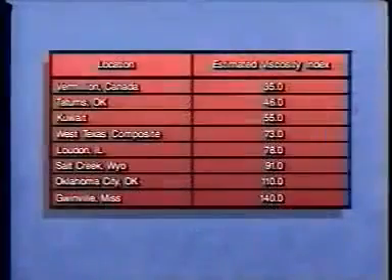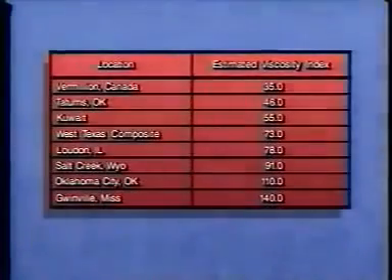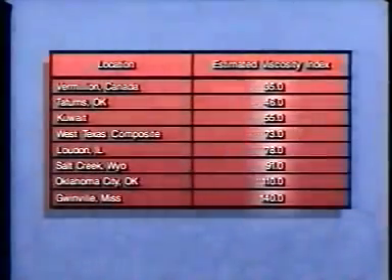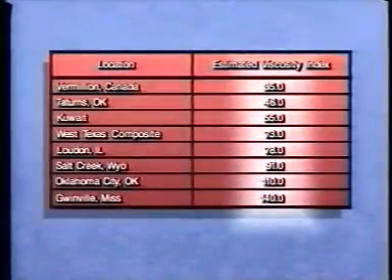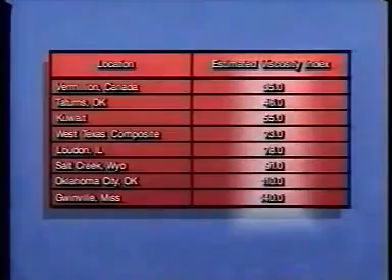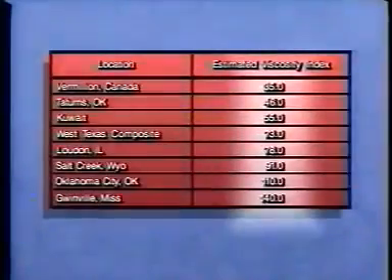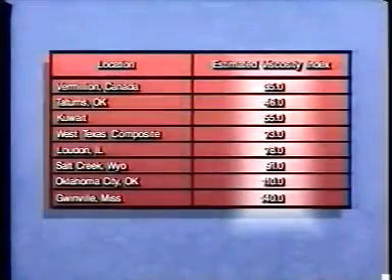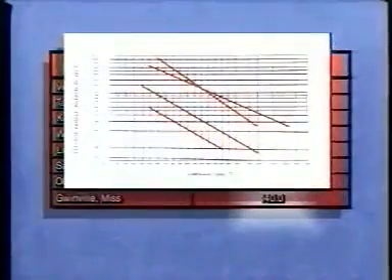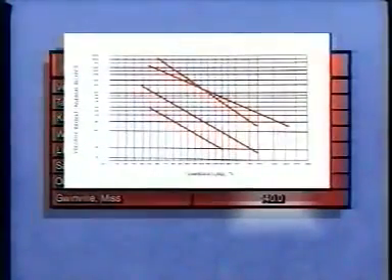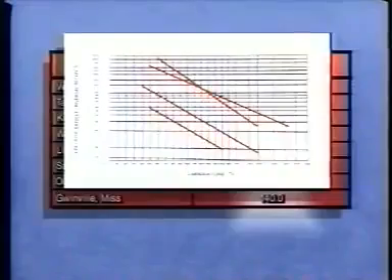There are two ways to determine how temperature affects the viscosity of an oil. First, the viscosity index indicates how stable the viscosity is with temperature changes. The higher the index number, the less the viscosity changes. The second method is the temperature viscosity graph. The workbook will go into more detail on how to make use of this graph.